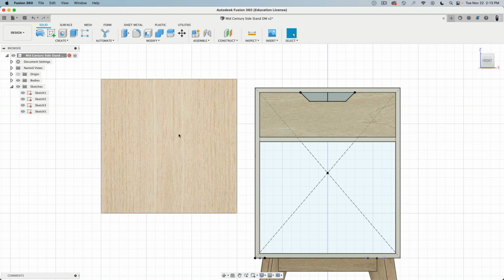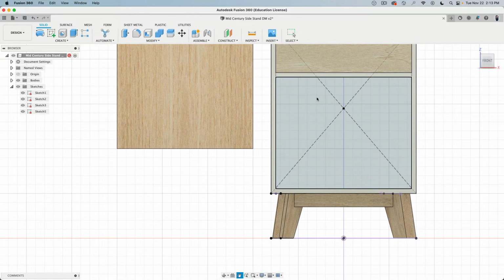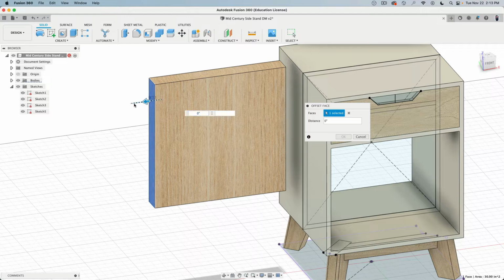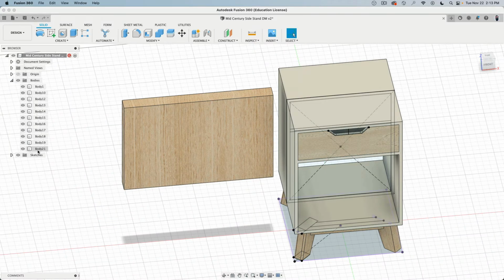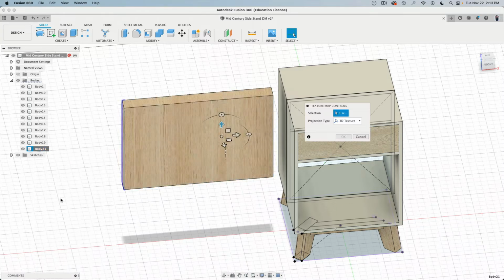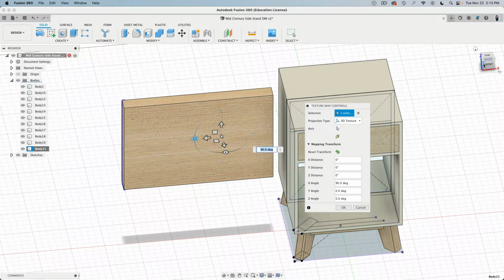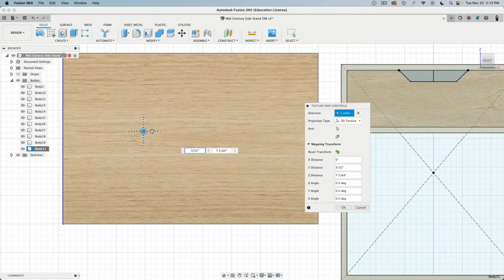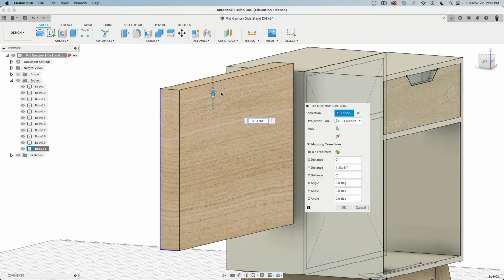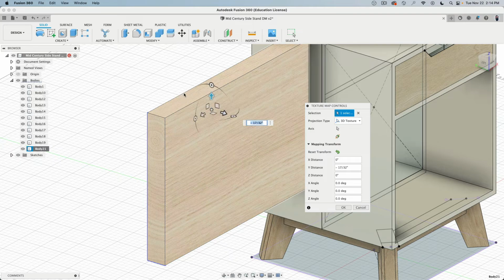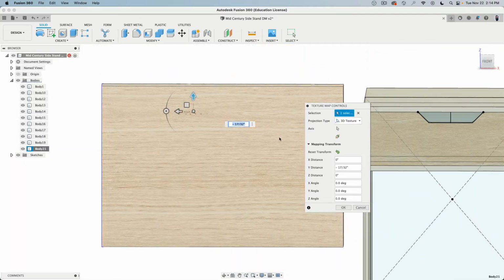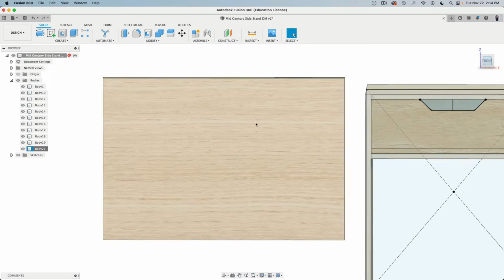If I go to the front view, now you can see the grain has the wrong orientation, but it's fine. Easily this piece I can map onto here. So this has to be bigger than the biggest surface we textured in our model. So maybe I will even make this a tick bigger, just to show you how easily it is to develop the veneers. The wood material is also rotated. So I will select the object, right click, texture control, and just rotate it. Very nice. Then I can go to side view, move this around. I can go to this view, maybe here and there. I have now actually also the rings. You see how I can play with everything and create individual screenshots from this much bigger piece. Okay, cool, no?